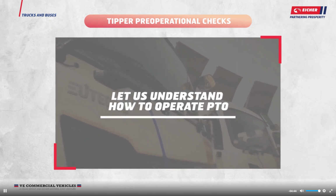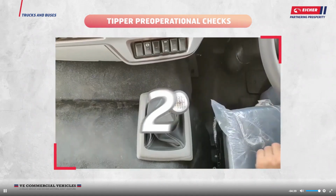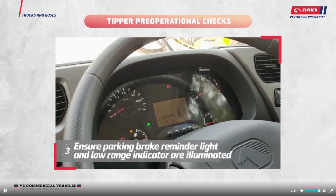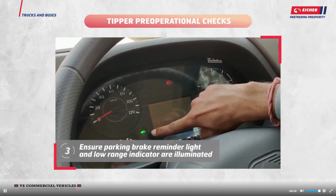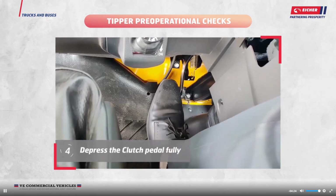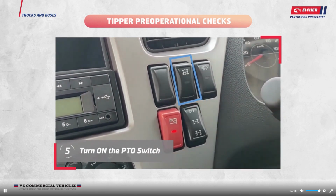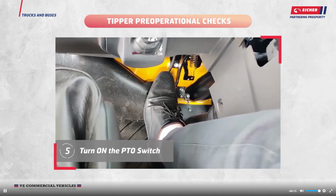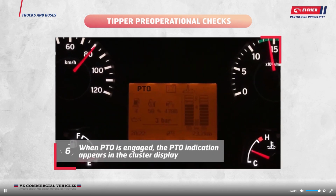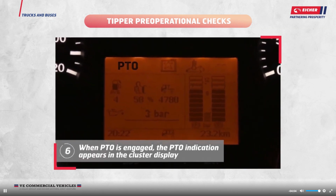Let us understand how to operate PTO. Apply the parking brake. Ensure that the gear shift lever is in neutral position at the low range. Ensure that the parking brake reminder light and low range indicator are illuminated in the instrument cluster. Depress the clutch pedal fully. Then turn on the PTO switch. PTO starts working once the clutch pedal is released, which means that the clutch is engaged. When PTO is engaged, the PTO indication appears in the cluster display, as well as the light glows in the PTO switch.